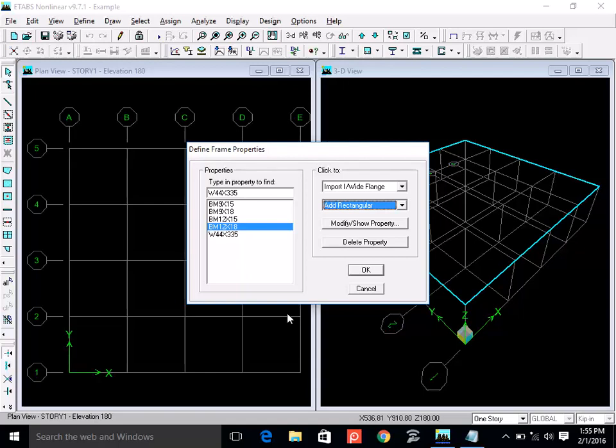The way you learn it, when you go to the design office as a fresh structural engineer, you study their previous designs. Their drawing sets are available from the previous project. So first thing you should do is you should ask for the drawings of previous projects. So from the previous designs, you note down these basic things, that what sizes they are using, and what is the format of the drafting, and other things, and how they write the general notes and other stuff. So you will learn that what is the practice of this company, and then you can follow the same practice.